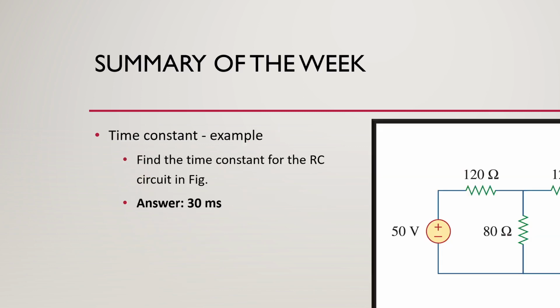So this is a particular circuit, and this is one question. In this case, we have to find out the time constant of this particular network. This is an RC circuit, right? You can see that there is a voltage source, but if you ignore this for a moment, you can see that there is only one capacitor, which is connected in some fashion with the resistors. So there are only resistors and only one capacitor, right? So it can be said that it's only a first order circuit.